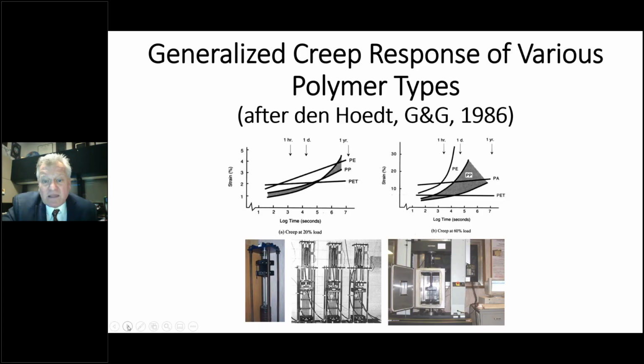You see the 3 different types of creep here. Conventional creep on the left, time temperature superposition in the center, and then subsequently on the bottom, stepped isothermal method. All 3 of these have application into this area and are addressed inside the guide for correlation.